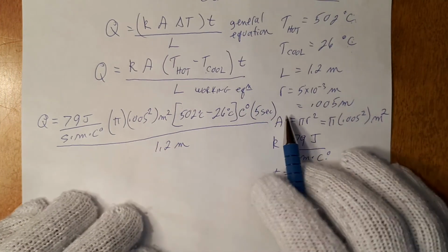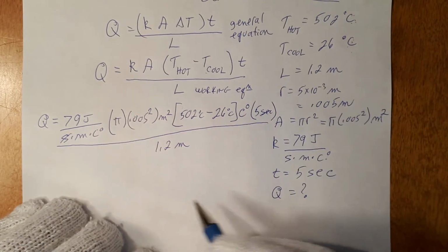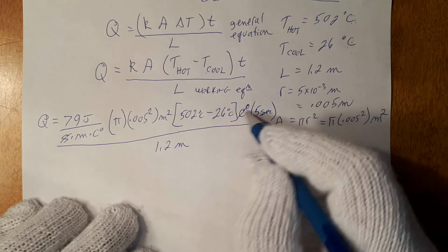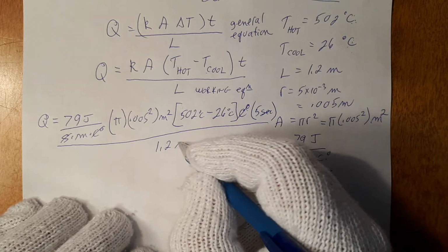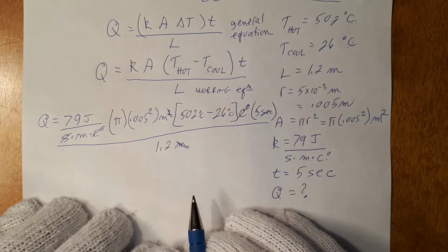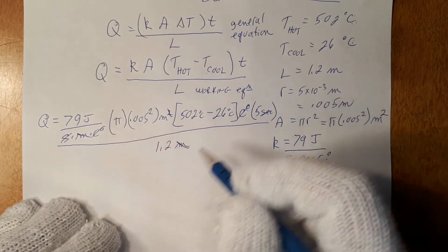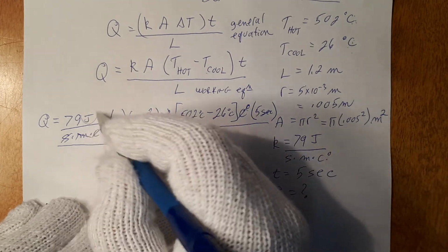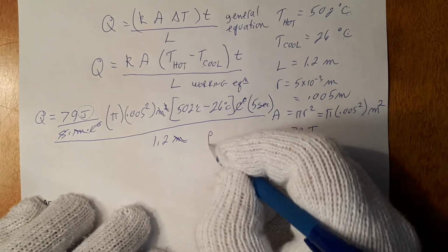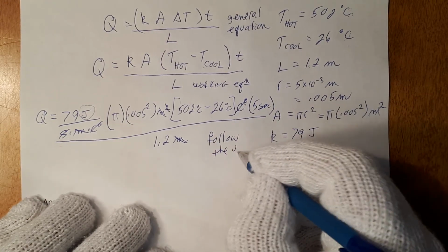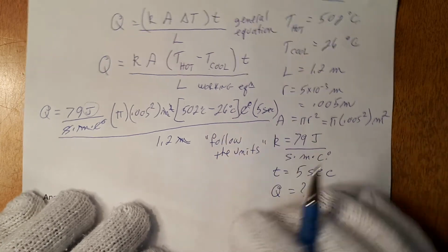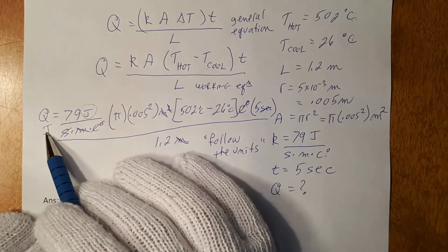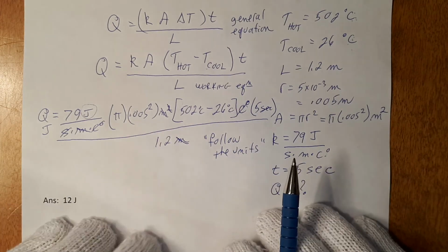Let's look at the units. I have seconds, and seconds in the denominator cancel out. Celsius degree, ignore the ones that are inside the brackets. It's Celsius degree when the subtraction is made, and Celsius degree. We have 1 meter down here and 2 meters on the top, leaving us 1 meter, and there's 1 meter in the denominator here and 1 meter left over. And all that's left over in the units is the joule. And I've said this before, follow the units. The unit for heat energy is a joule. So joules on the left-hand side, joules on the right-hand side, everything is ready to go.